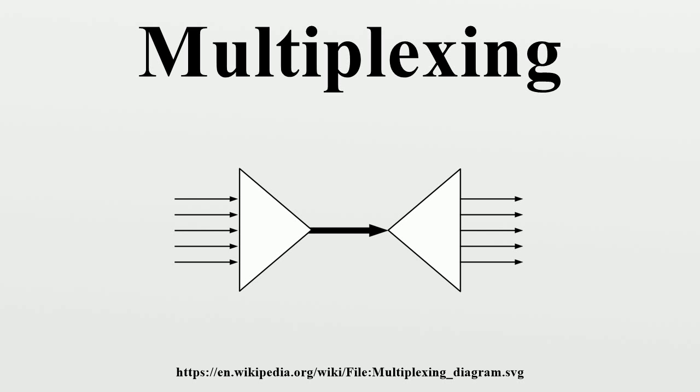In several of these systems, the multiplexing results in an MPEG transport stream. The newer DVB standards DVB-S2 and DVB-T2 have the capacity to carry several HDTV channels in one multiplex. Even the original DVB standards can carry more HDTV channels in a multiplex if the most advanced MPEG-4 compression hardware is used.